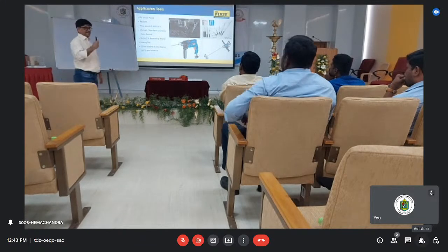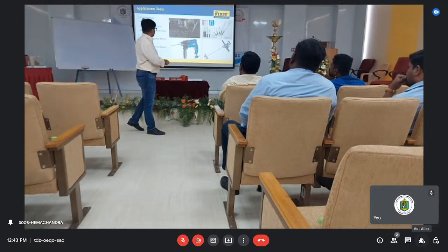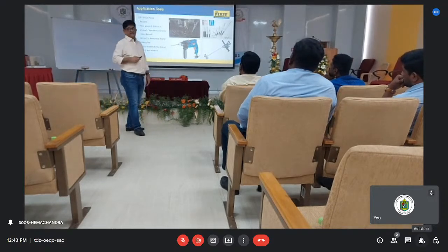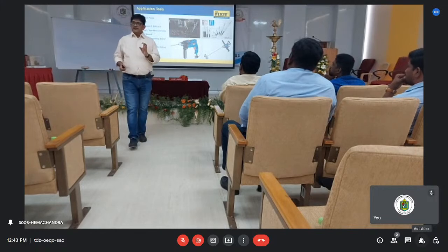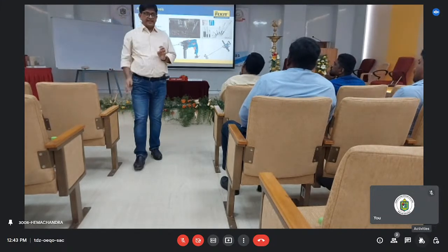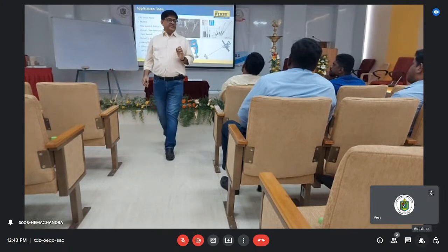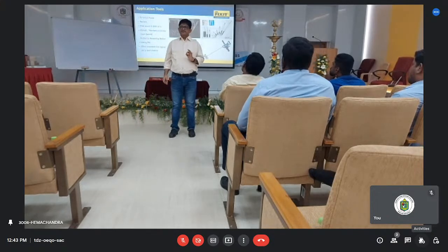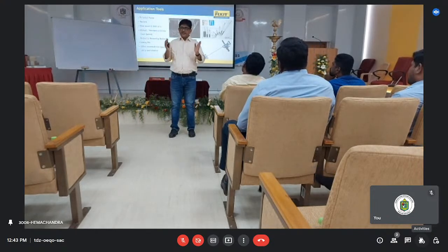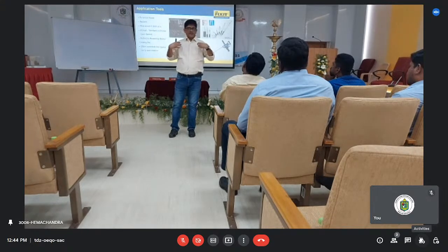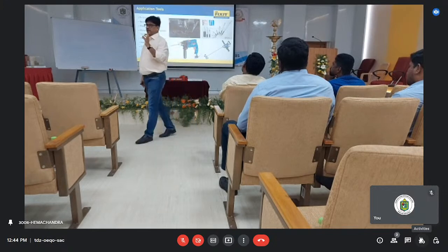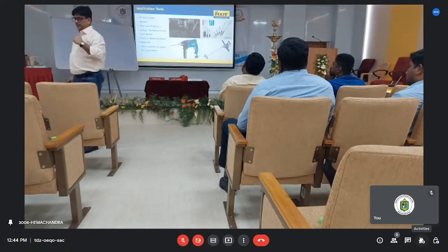These are different sizes of injection packers, called non-returnable injection packers. Non-returnable means the material which I am putting inside should not come back. Because when you are doing an injection in concrete, there is back pressure. So there should always be a non-returnable valve inserted, so the material should not come out.